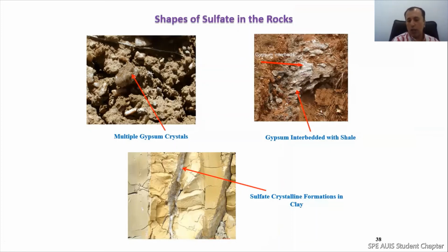When it's dissolved, that will leave cavities between the clay rock layers, and we will have a lot of fluid loss. Plus, that amount of salt will reduce the rheological properties of the cement slurry and the drilling mud.